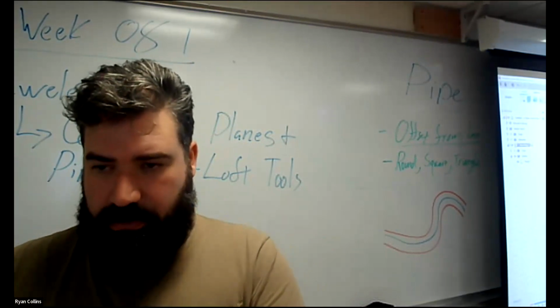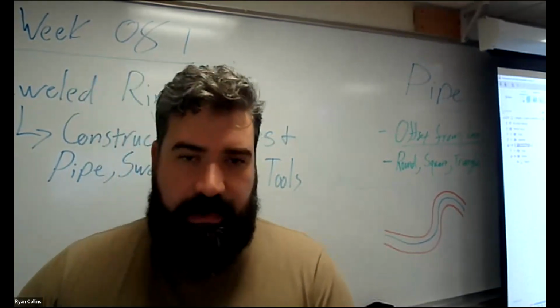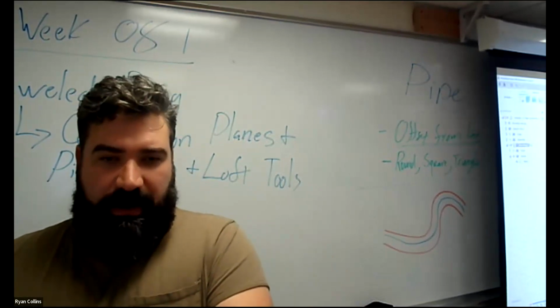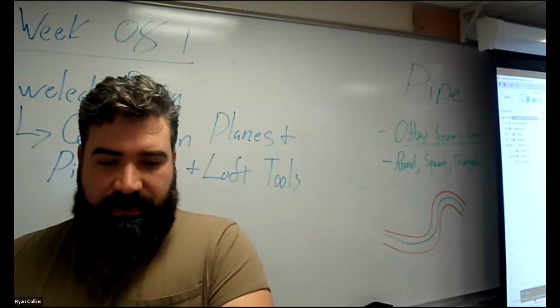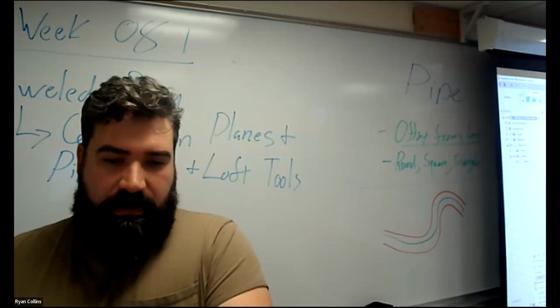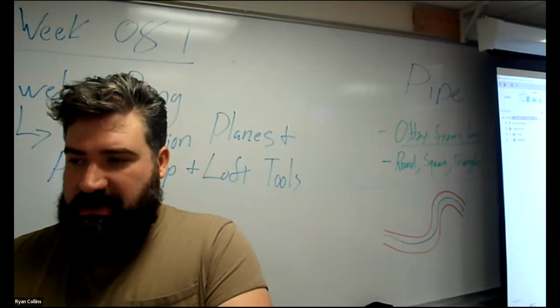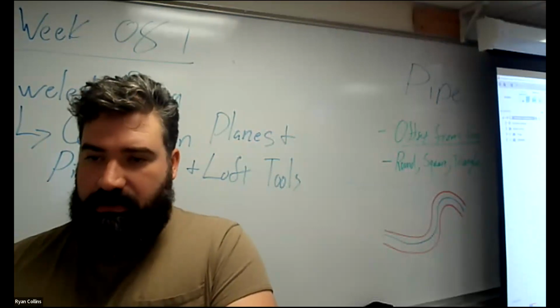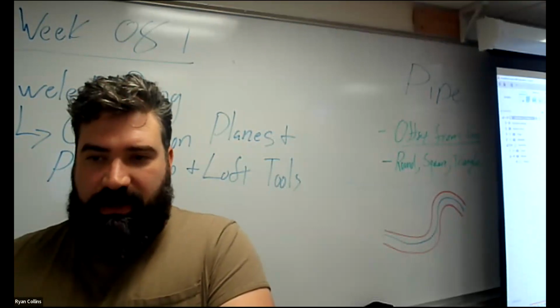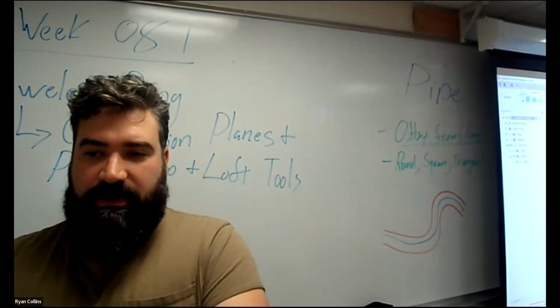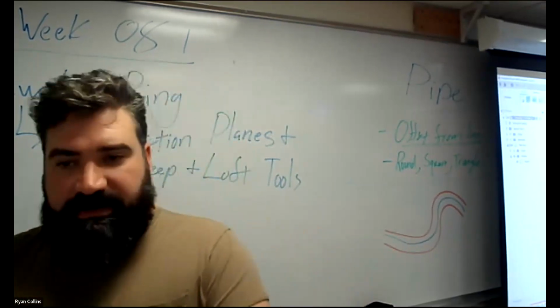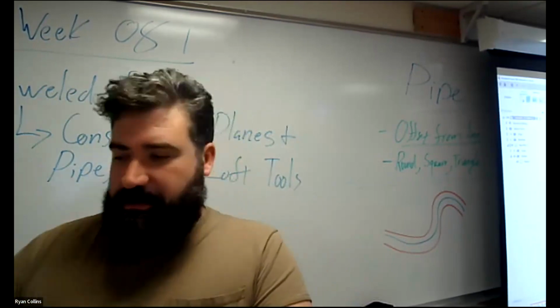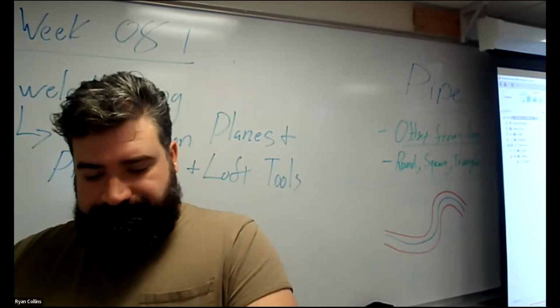Pipe ring. Okay. And ultimately, if you want to go back and shrink that, activate everything, go back to that original pipe tool, edit feature, make that, I don't know, should have been 1 millimeter big. There you go. Let it recalculate. Now you got a finer lattice work. So a neat way to add some stuff to it. And this is basically how we're going to go for a couple of examples here.